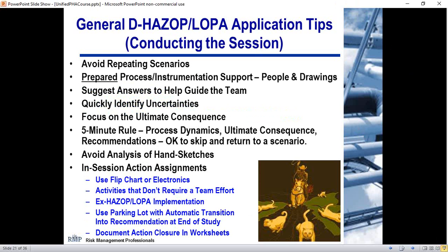That's not appropriate. For the HAZOP and LOPA, it's all about the scenario. How do the protection systems respond to upset conditions, and are they adequate? So instrumentation folks need to come in prepared. Instrumentation drawings, the functions need to be apparent from the P&IDs or from cause and effect diagrams, and this is critical towards a proper HAZOP and LOPA assessment.